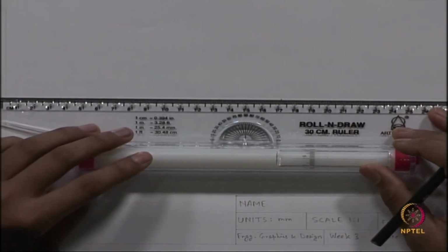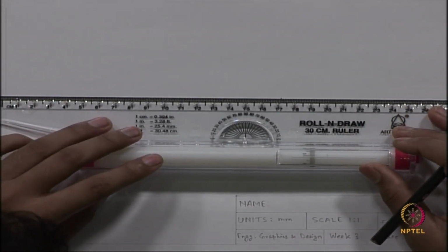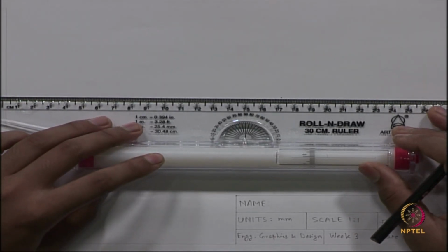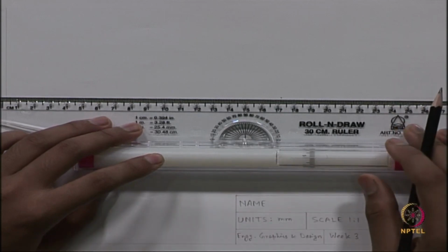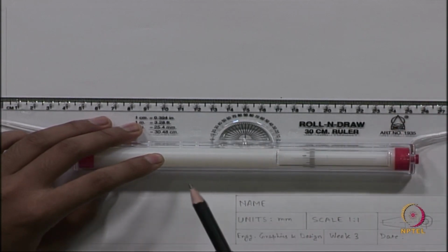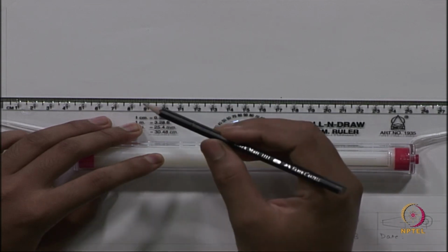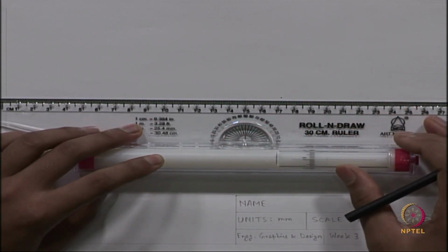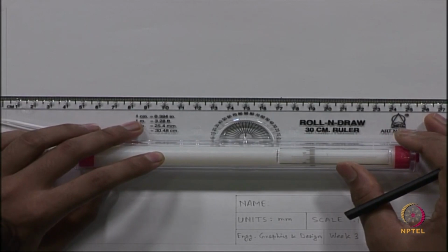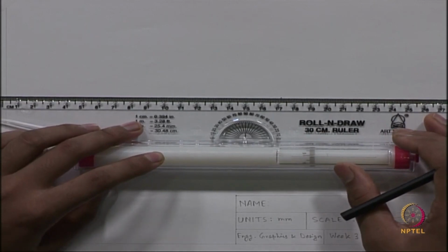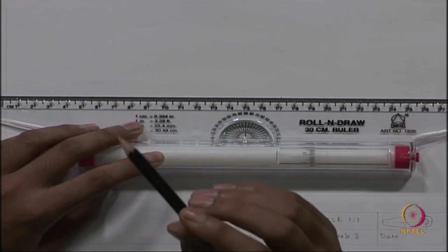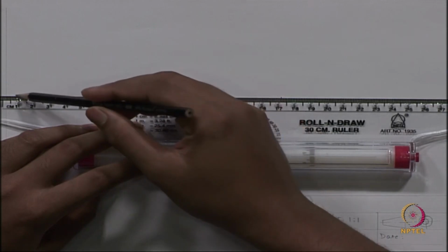Here we have to first draw the reference line. For drawing the reference line, we will draw only the horizontal reference line, because only the front and top view is asked. So, that will be in horizontal plane and vertical plane, and the intersection line between horizontal and vertical plane is the reference line, and that is horizontal in our case. And this reference line drawing and these kind of things I will be doing using H pencil, the light construction pencil.